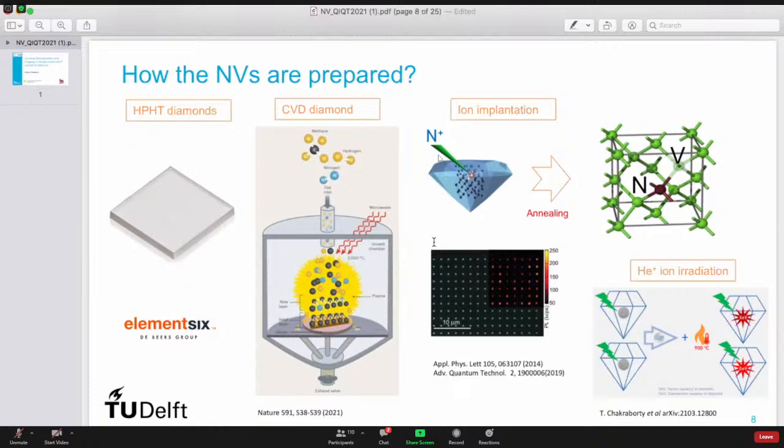The ratio of methane to hydrogen is typically 99:1. And then there is a heating element which ionizes the gases at very high temperature. A microwave is one way of doing it. So this is called microwave assisted chemical vapor deposition.